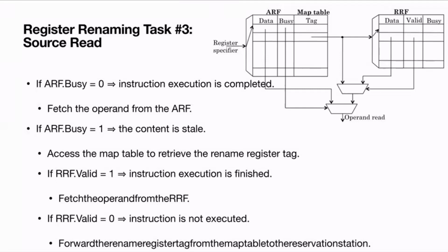So these are the three important components: register renaming, reorder buffer, and reservation station. All three R's are the main components of any superscalar processor, which supports execution of instructions in out-of-order fashion, identifying independent instructions, and also supports speculative execution and so on. Right? Do you have any questions?